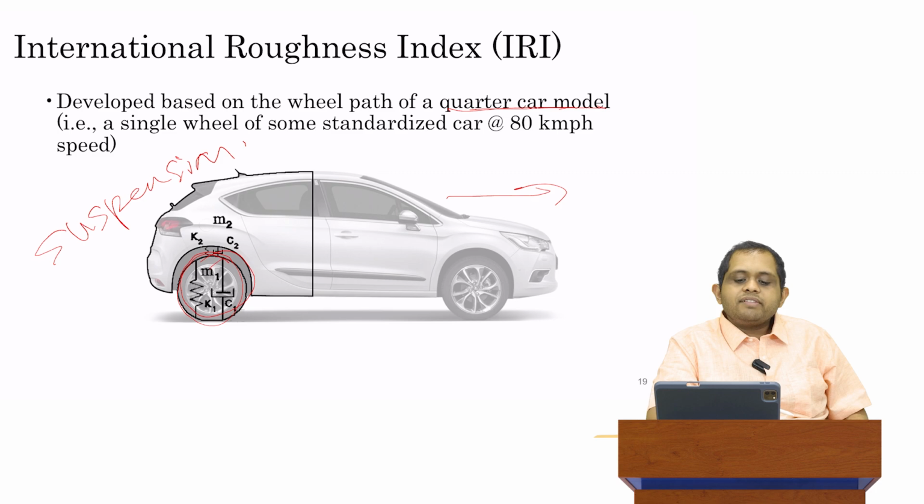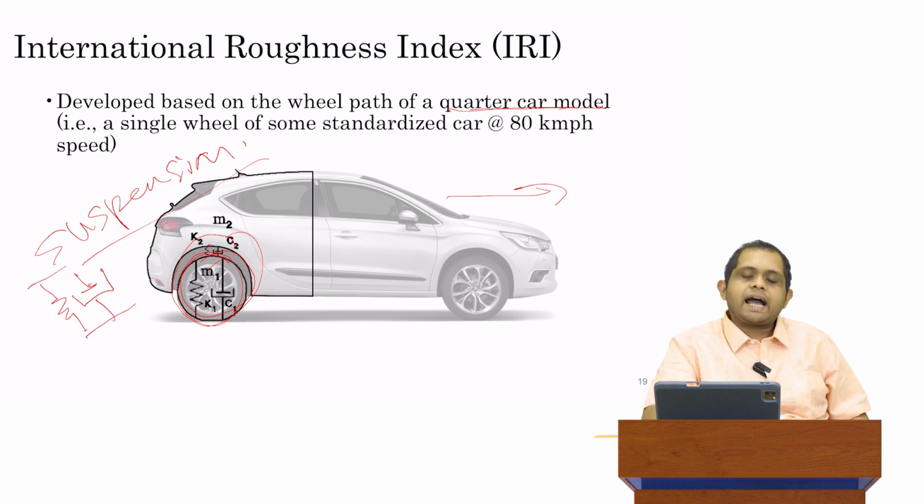So the suspension is basically a series of springs which dissipate any kind of undulation, any kind of unevenness on the road. So if you experience some road which is a little rough, the roughness is dissipated somewhat by the presence of the suspension. Now, mathematically speaking, the suspension is generally shown using what is called a spring dashpot model. So you have a spring and then you have another mathematical object called a dashpot. This allows you to create a mathematical model of the tire and the vehicle.